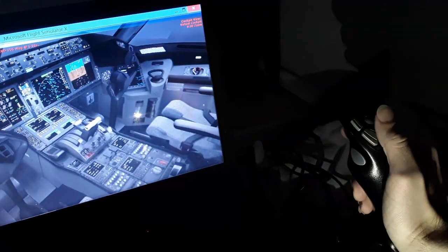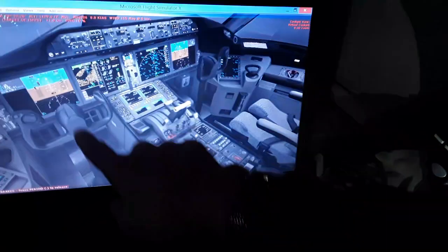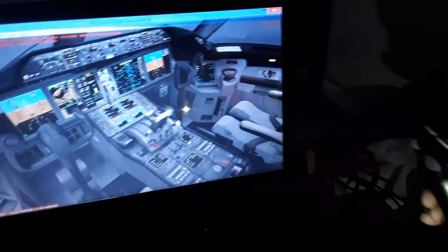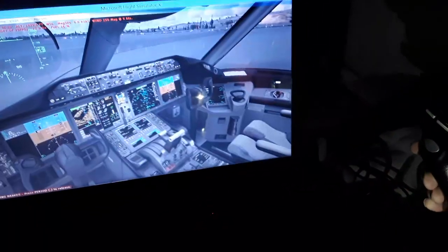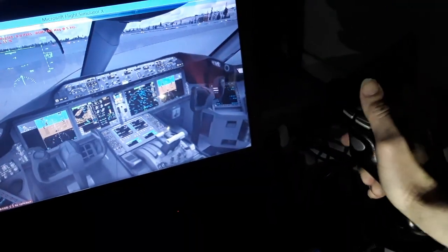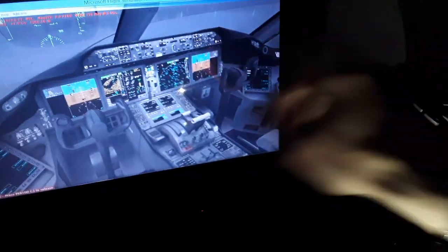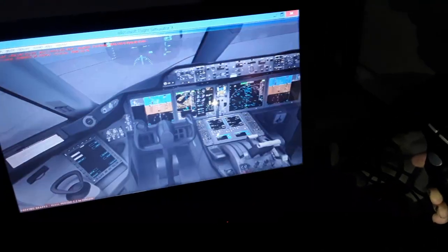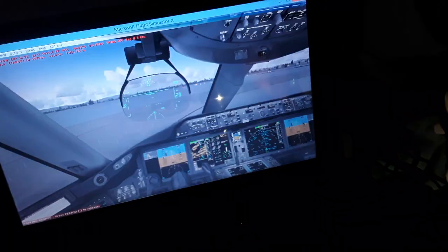You see the side stick deflection is proportional to the yoke. Both sides are interconnected for the flight controls for climb and descent. Also the control column, here the control wheels. The control column is for the elevator for climb and for descent, and the control wheel is for making turns left and right using the ailerons and the spoilers, and the rudder pedals using the rudder, the vertical tail of the aircraft. And also for nose wheel steering, the ground is interconnected with the tiller until some airspeed.